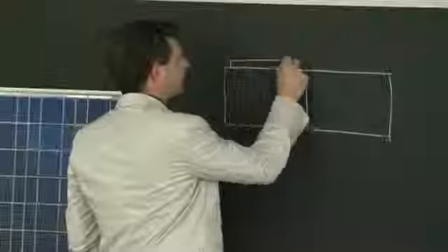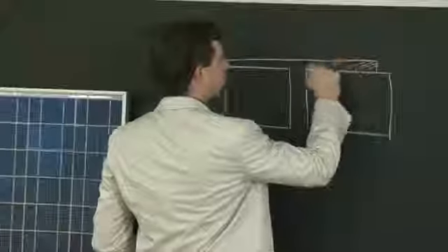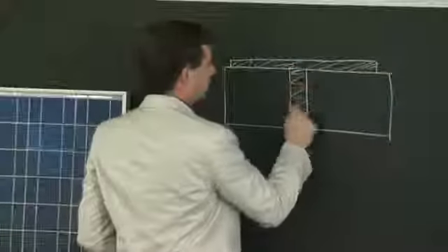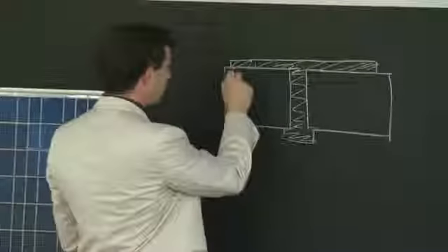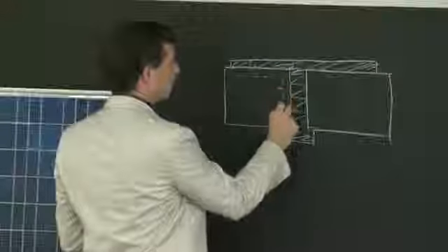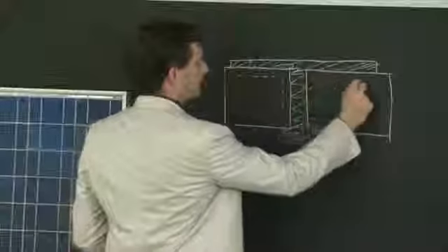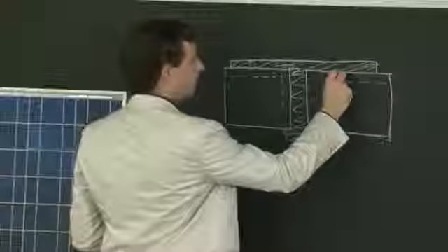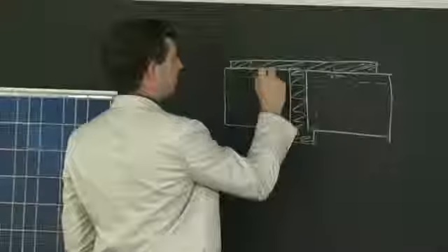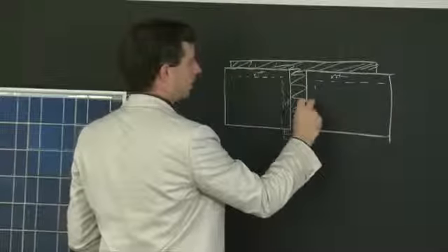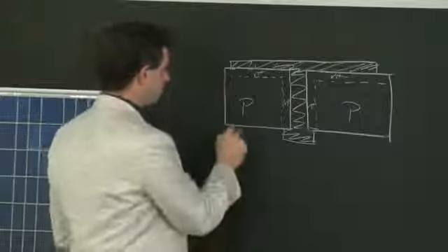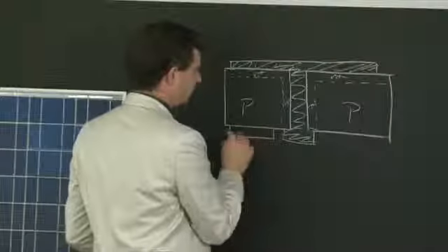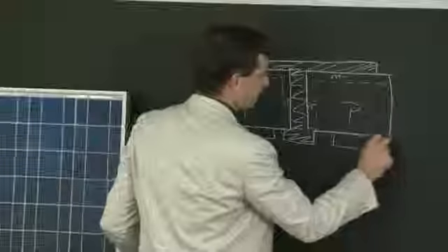And then you could have your contact metallization, say, for electrons right here. You could have the PN junction like this. So this here could be your N plus material. Again, N plus material. This by effect would also be. And you could have your P materials over here. And you could make contact to the back right here and contact to the back right here.